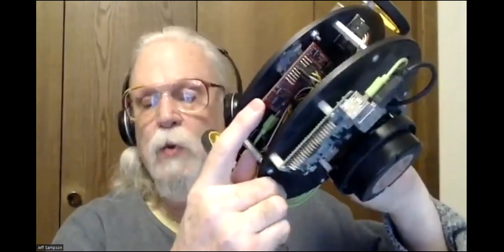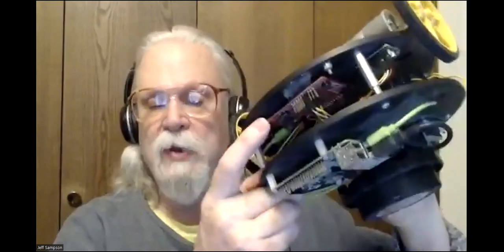It'll do 2 channels of quadrature decode, so you just hook it up and those just work. And all the ST Micro parts seem to be able to do it, I'm going to say all of them, and that might come back to bite me, but even that little blue pill, which is like the older Cortex-M1 or something, will do it too.